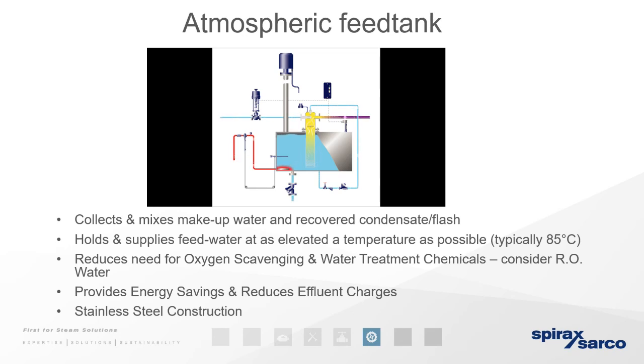Secondly, the boiler will respond more quickly whenever there is a demand for steam, because if we supply the boiler with cold water, we will suppress the boiling rate, and therefore we will have a boiler that does not act on the demand if required. And thirdly, at a higher temperature, more of the entrained oxygen and non-condensable gases have been purged off, meaning that you will have lower costs of chemical consumption.